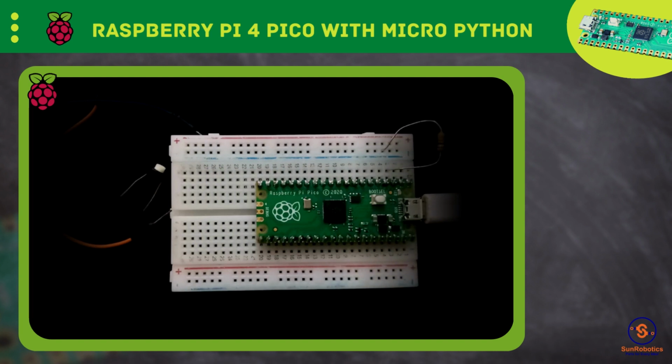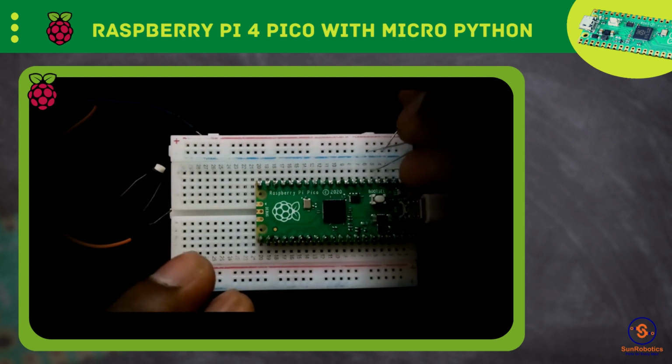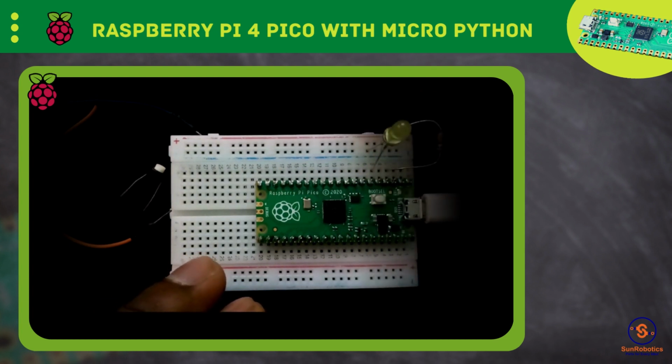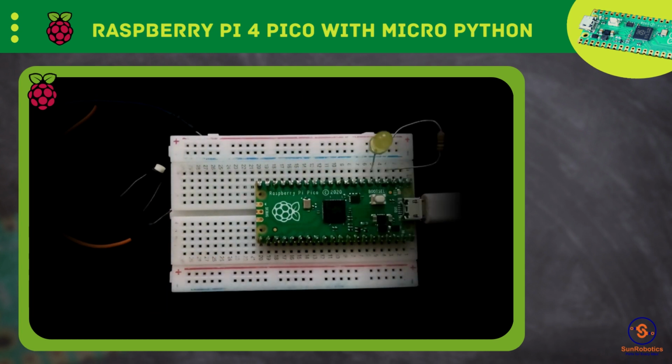We have to connect it properly. I'm finding the pin number 1, 2, 3, 4, 5, the 5th one. The longer leg goes there and the shorter one goes to the ground. So I just connected it like that. Now the LED part is fixed.